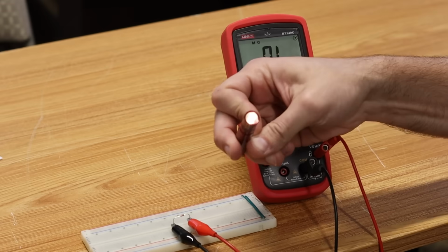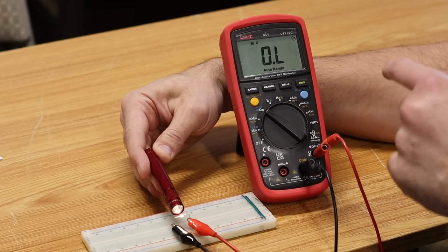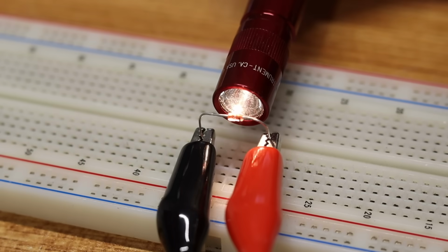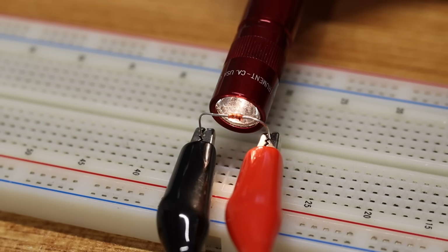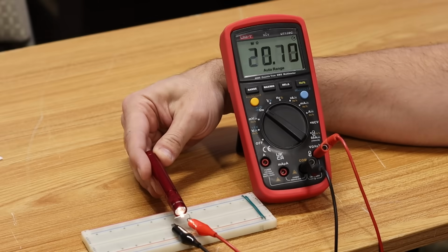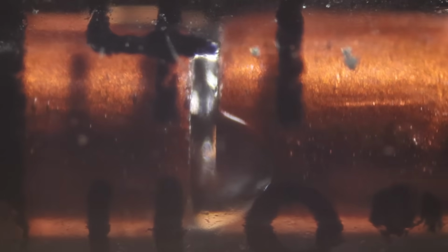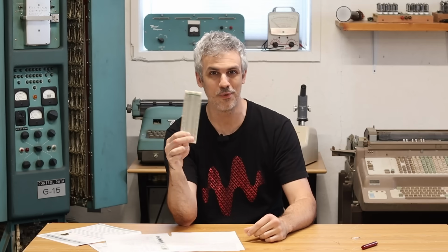However, if I take my little flashlight here and I shine it straight into the glass package, oh, look at that. We saw it just briefly there. It's really hard to get the photons to strike that p-n junction directly, but there we go, all the way down to like 7 megaohms there for a second. So just by putting some light onto the diode, I'm starting to change the reverse breakdown properties of this diode. Since all diodes have this depletion zone, and striking that zone with photons changes the breakdown voltage of the diode, all diodes are in fact photodiodes. But this 1N4148 is actually a really, really terrible photodiode.